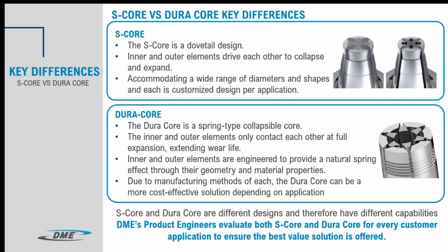And so as the mold opens and closes and moves the inner segments, basically it's driving the outer segments of the core. So it's a constant mechanical interaction between the inner and the outer cores. Through that, though, the S-Core is capable of accommodating a very wide range of shape applications and a much greater undercut, depending on the application, as we'll see as we go through the presentation here.